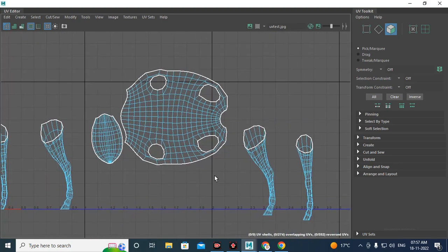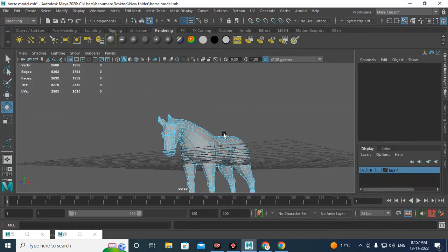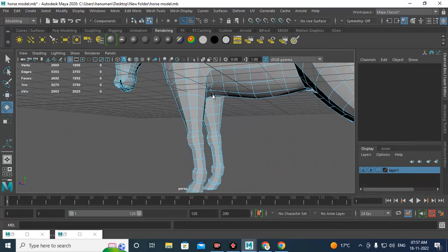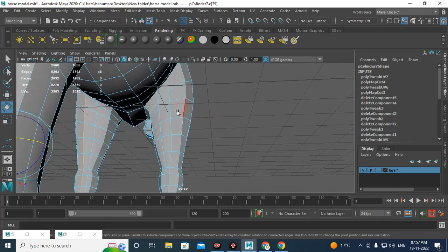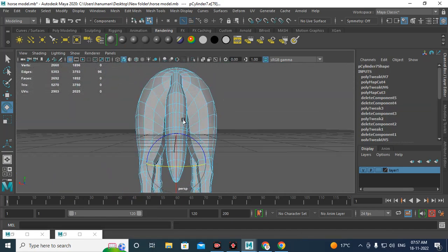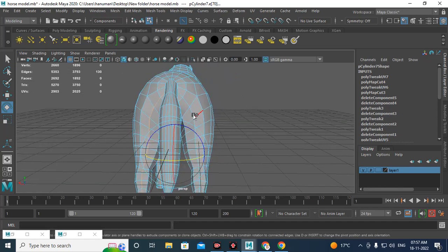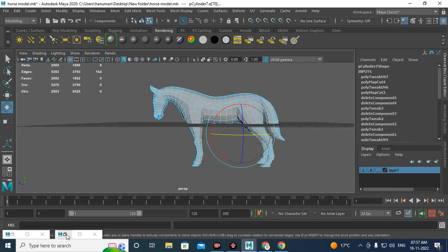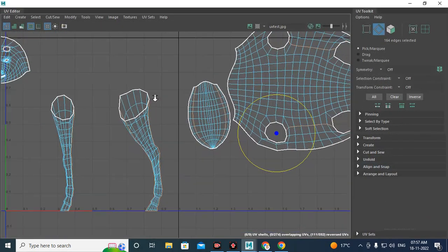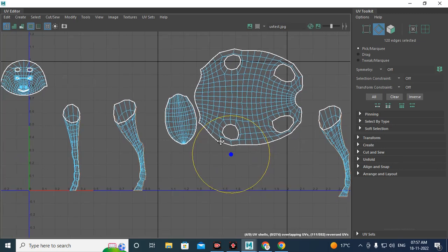This one. See, only for the legs again you have to select the back side part. In this UV you have to select edges here, and here, and these position edges. Go to the UV editor, and whichever you don't want to cut, just deselect with control and drag here. That edge loop is selected in all the places, right?